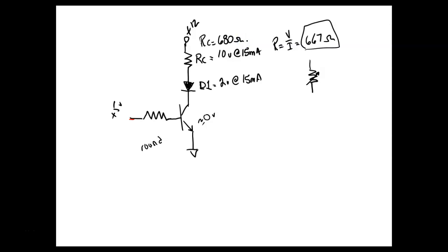Okay, so now I got the size. What else do I need to know about that resistance? Tolerance we're not going to worry about. It's a 5%. We know it's not going to burn up the LED if it's 5% high or 5% low. In fact, you wouldn't even be able to tell the brightness. What else do I need to know?